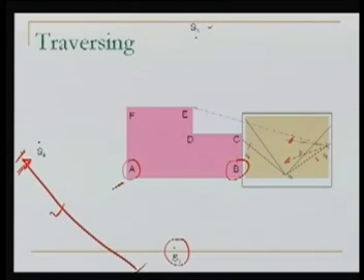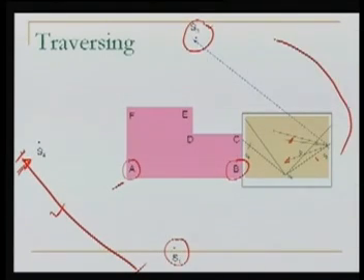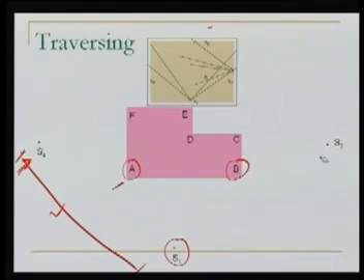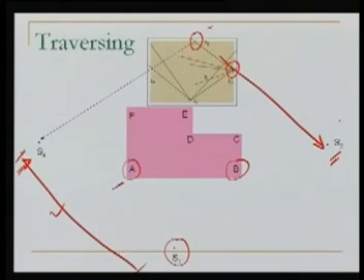Well, next to E, and then we will again take a site to the station S3, because we want to now shift our table here. Same intersection we would like to do by shifting the table to S3. Well, the table is now shifted to S3. Once the table is shifted to S3, again we will orient the table here by backsighting. By backsighting this S2, because S3 and S2 both are known on my table.